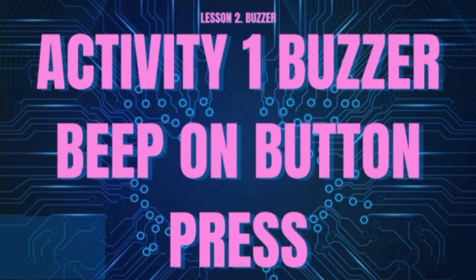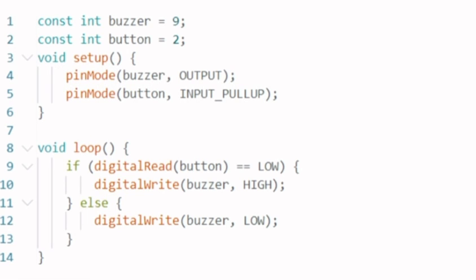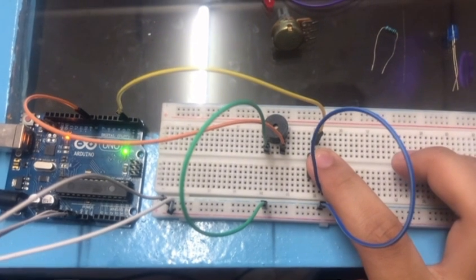In this activity, the buzzer's negative leg is connected to GND while the positive leg is connected to pin 9. The button's right leg is connected to GND and the other leg is to pin 2. When the button is pressed, the buzzer beeps, showing how a simple button can control sound output.